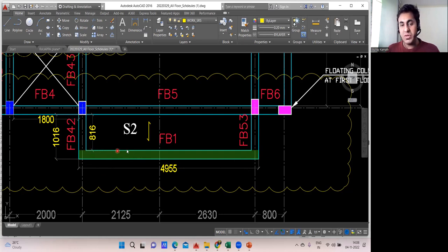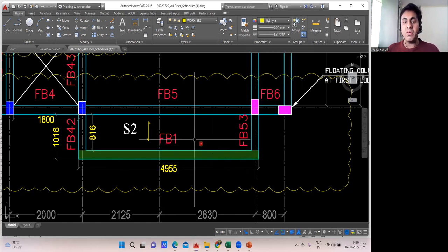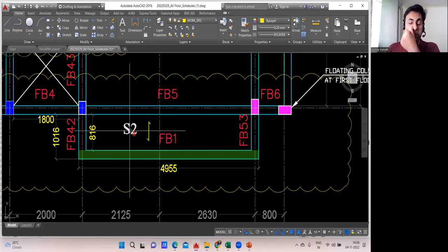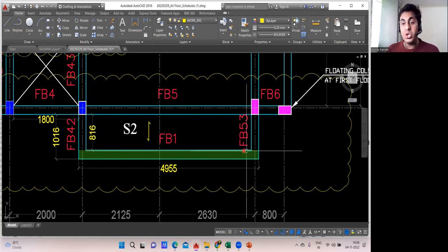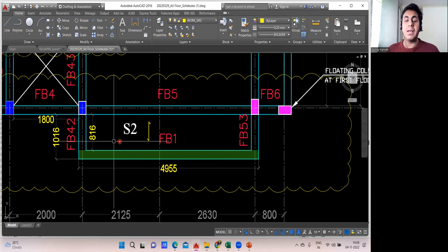Whereas in this part, it is going to be inside shuttering. Why? Because you have a slab. How can I identify that there is a slab? They write it in this way: S1, S2. You can see S2 is written. That means a slab is here. Fine. So whenever you find the depth of this, you cannot take directly 0.35. What you're supposed to do is, from the depth, whatever the thickness of your slab is, you need to deduct that. Now the thickness of the slab in this project, everywhere it is 150, whether it is S1, S2 or S3 slab.